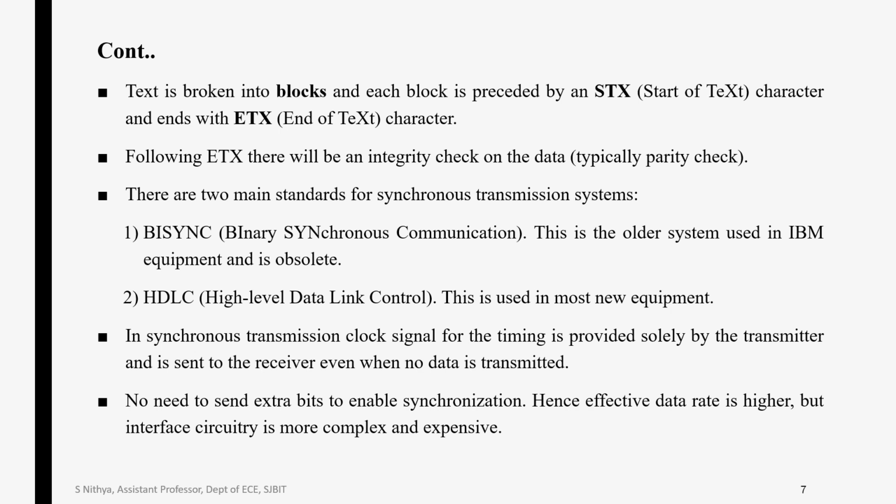The text is broken into blocks and each block is preceded by STX, which is nothing but a start of text character, and ends with ETX, which is nothing but the end of text character. Following the ETX there will be an integrity check on the data. It is typically a parity check bit.